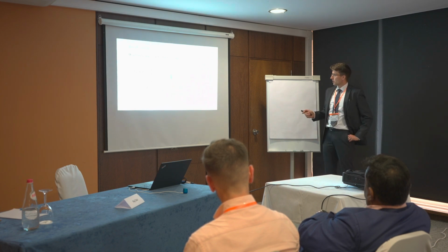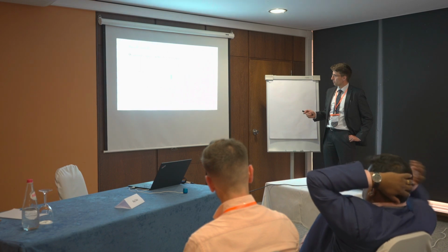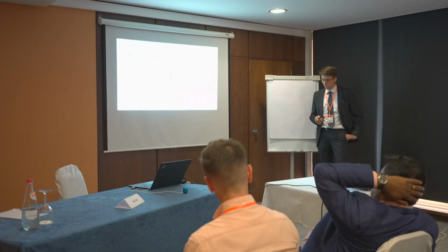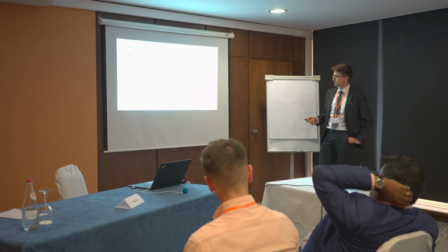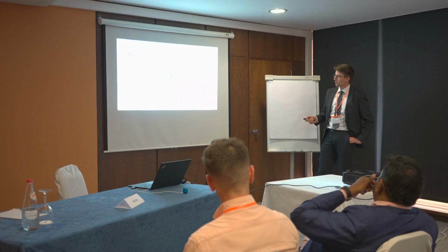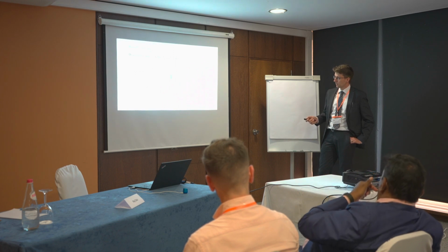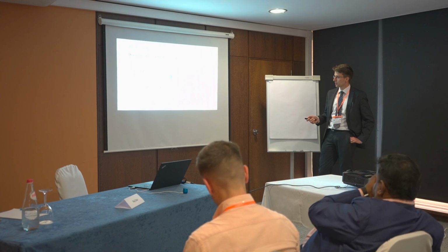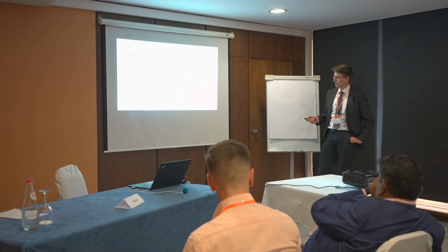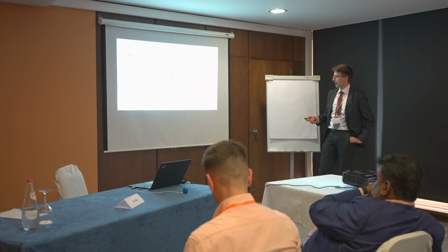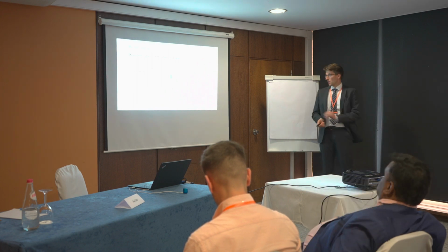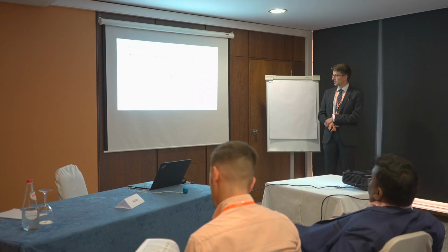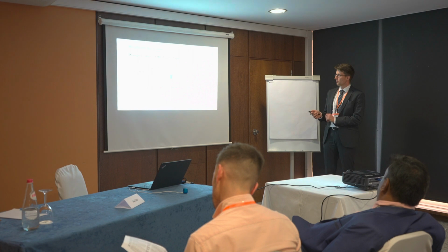And then we can see a quite linear relationship, and we can calculate the slope of this linear relationship. And here you can see what was assumed. We assumed that the optically measured displacement is of course equal to the calculated displacement of the strain gauges, and this is the actual equation here, and this K factor was calculated. So this is basically the dynamic calibration here without a pulse shaper.